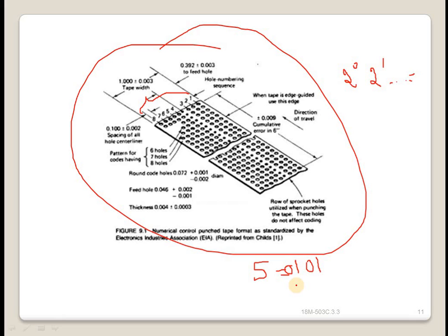Using an NC drilling operation as an example, a block might contain information on the x and y coordinates of the hole location, the speed and feed at which the cut should be run, and perhaps even a specification of the cutting tool. To separate blocks, an end-of-block symbol is used.